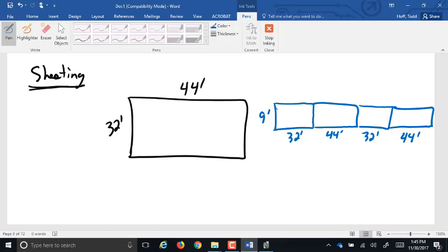Well, the biggest thing is the floor thickness, right? You have to sheet across down below the floor joists. Now we know the floor joists are more than a foot thick in most cases, but also usually with the way your trusses, your overhang on your trusses comes below the top of the wall. So the top 3 or 4 inches of your wall are usually blocked by trusses. So you don't have to sheet all the way up to the top of that exterior wall.